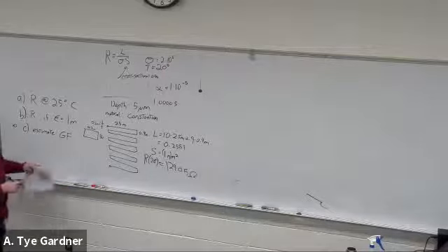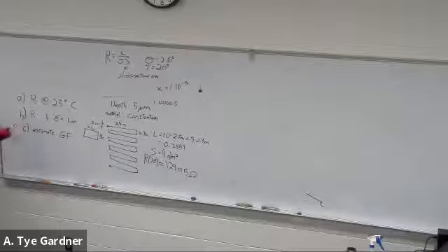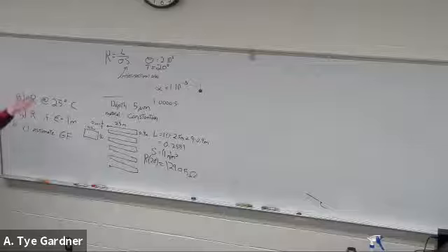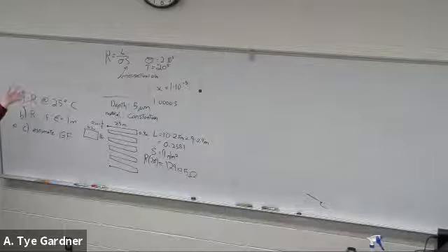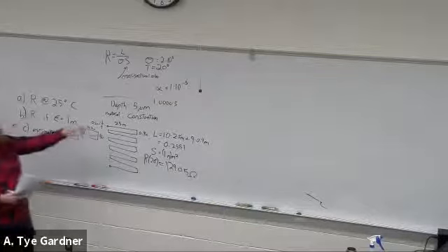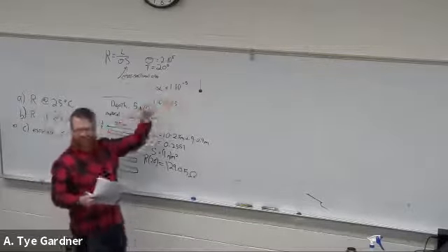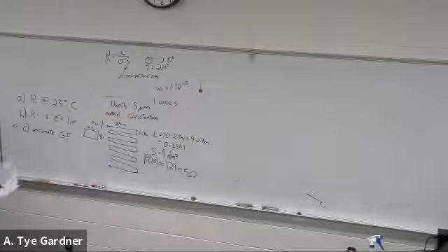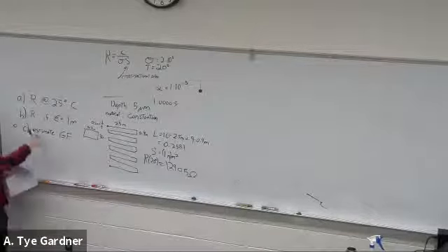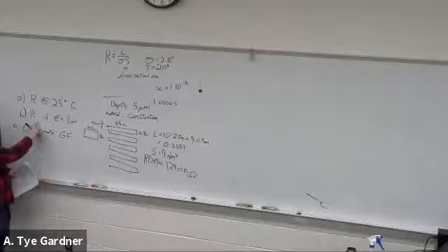Anyways, yeah, so you can do the calculation again if your alpha gets much higher, right? We can do the calculation like, let's pretend that the strain gauge is actually made out of doped silicon and its gauge factor is 90,000 instead of nothing.